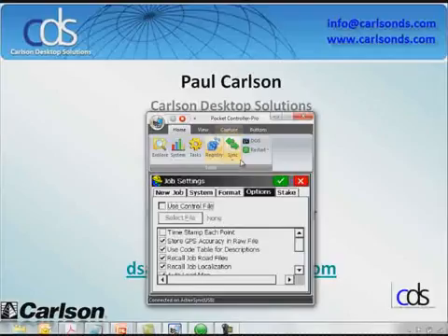So under the File menu, Job Settings, I have to remember where it is here. It's under Option, Store GPS Accuracy, timestamp each point. Great. If that's turned on, that gives me this TM note, and that works for total station or GPS. And then whether that's turned on or not, the log raw vector stores that GPS clock time.